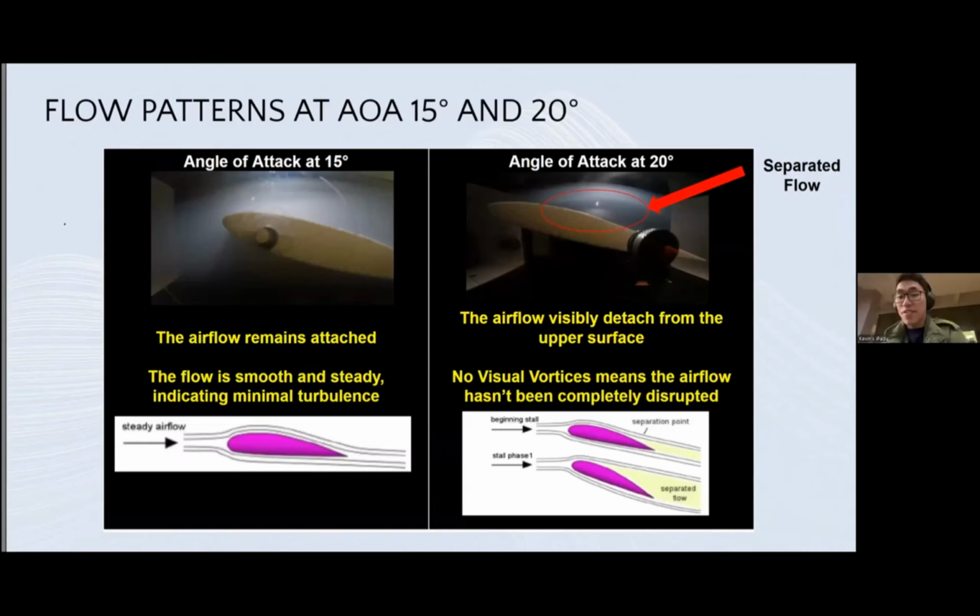Yeah, so on the left is the airfoil at an angle of attack of 15 degrees. The airflow remains attached along the surface with no visible signs of separation. The flow is also smooth and steady, indicating minimal turbulence and stable performance. The diagram on the bottom left illustrates steady airflow with attached streamlines representative of this condition.